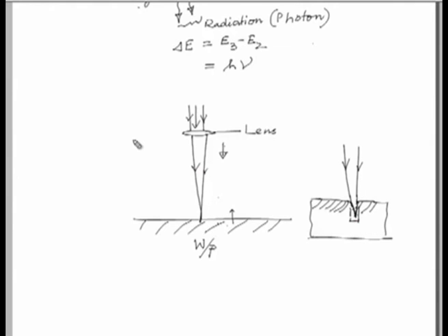This possibility is there in case of LBM and therefore, if the application is for precision products, then this may not be a very suitable process to be used for cutting or drilling micro holes.